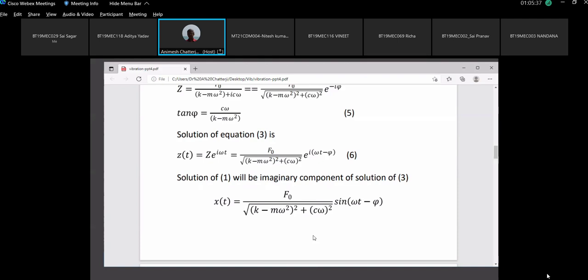But what is the disadvantage of damping? If damping is there, there will be wastage of energy. Some part of the input energy will be lost through damping. But damping will be able to control the vibration amplitude. So from my side, the most important sentence is, if damping is 0, never allow omega to become equal to omega n or come close to omega n. Sentence number 1.